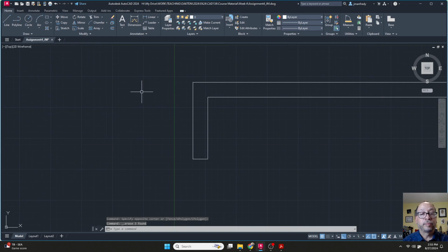Mirror command. Let's say I had a line right here, and I wanted to copy these walls to the opposite side of this line with the same orientation, but flipped over. I can use the copy command to move this over to here, but it'll make an exact copy. It'll look exactly the same. If I want to mirror it, like let's say pages of a book, I'm flipping it over, then that's the mirror command. Here's the mirror command here.